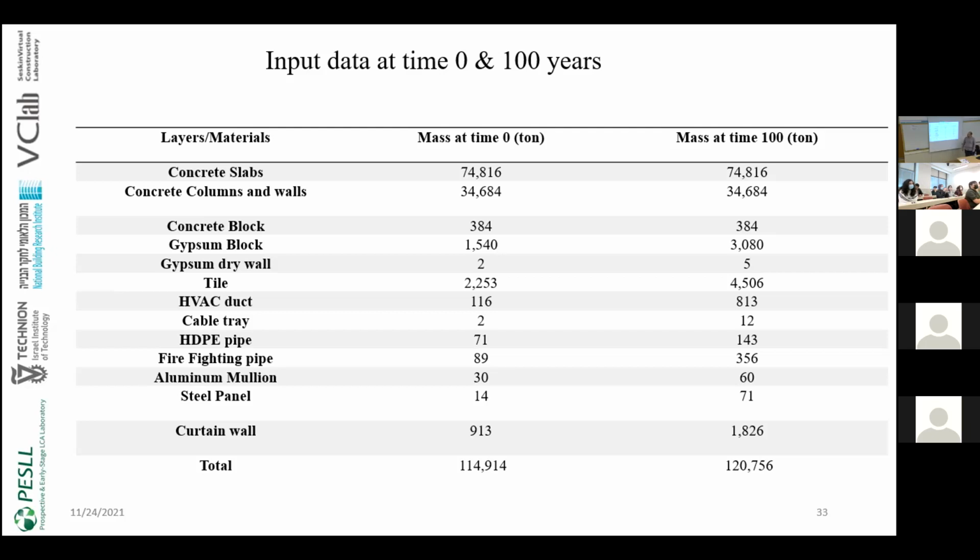Yeah, so this showed, as Sabrina mentioned, the transformational effect, how much the embodied greenhouse gases in the materials and the transportation of the material from the source to the project. Now, the second step is collecting some data related to the flow, which means we need to calculate the flow in the project by calculating all the start and finish dates for each activity, and we can calculate the construction flow index, for example, as a measure for the flow.